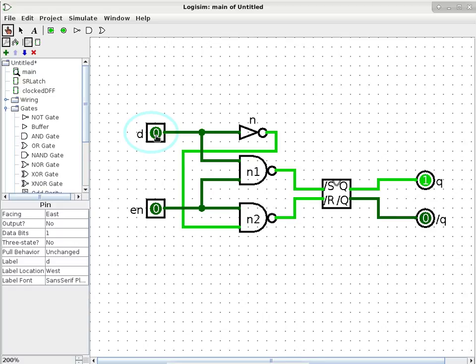So this is the most basic D flip-flop. And the reason why it's called a D flip-flop is because instead of having one pin to say set, the other pin to say reset, which is the job of an SR latch, now we have also two pins, but one pin specifies, should I change? Should I mirror the pin D, and then the D pin is saying what should be stored. Should I store a 0 or should I store a 1?